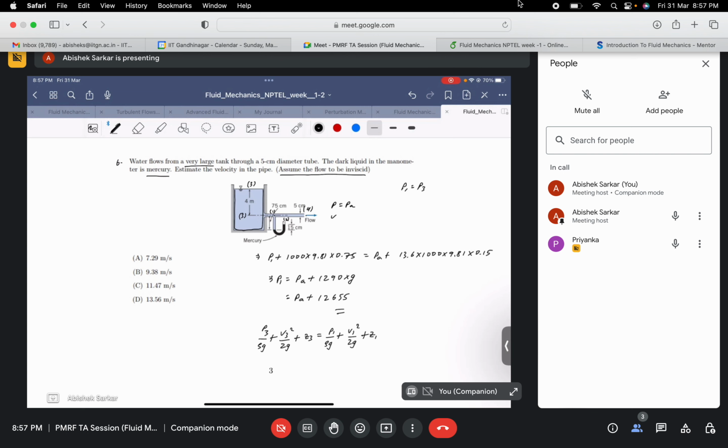You cannot assume like that, even if they are at the same height, because the geometry is different and the physics of the flow is different. One is ideally hydrostatic, and the other is a flow through a pipe with a velocity. So given these changes in the geometry, you cannot assume the pressure would be the same. Okay, sir. Yes, and that's why I guess that is where you have made the mistake.